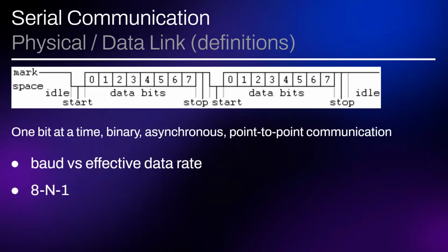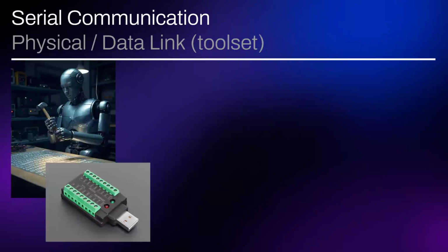In modern serial communications, I've never seen really an error come across a serial line. It just doesn't happen, and we're clocking at really high rates. I mean, we're really buzzing. So usually people set this as no parity, like we don't care. It's not going to happen. But anyway, if you see this 8N1, that's what we're talking about there.